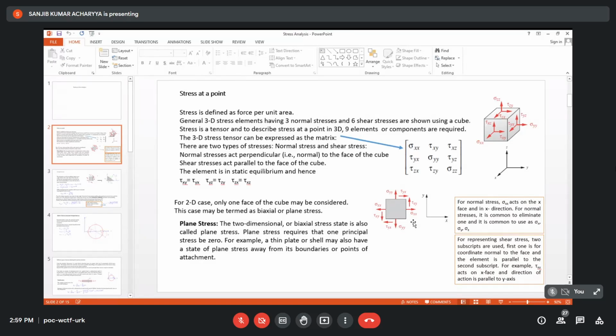This term is very important. In future, as a mechanical engineer, in case of material behavior, you will face this plane stress situation. Plane stress means that on that plane, stress can be represented two-dimensionally. That means in the perpendicular direction of the plane, there is no stress at all. It is convenient because 2D representation will require a minimum number of stress components. But I will not do it forcibly. If it is available, then I will take the advantage.